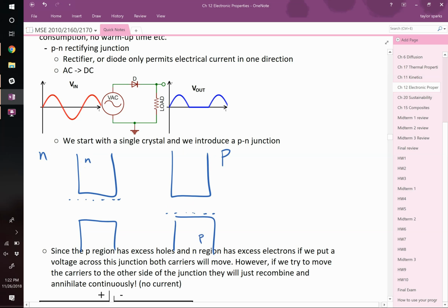If you bring those together until they touch, what's going to happen is this Fermi level has to be continuous. It has to become a flat line. So the only way that that can become a flat line when they're at different energy levels is something called band bending. Okay? So let's draw it. This was before. Now after this line has to be constant. So you've got your N-type material here. Let me just get rid of that. It's going to switch and it's going to look like this.